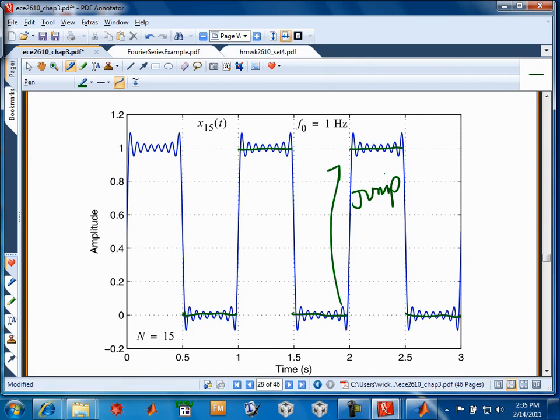it then kind of gets into a turmoil and it ends up ringing. So it overshoots, undershoots, and then tries to damp out in between. So it's damping down to a smaller value in here. But then the next discontinuity comes along and then it gets all whacked out again. It starts ringing again. And this is due to that discontinuity.